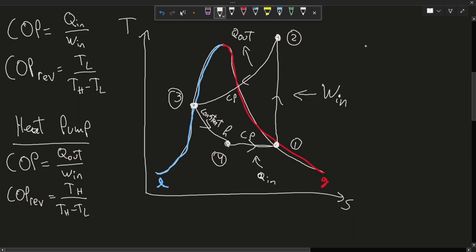One last thing. Unlike the Brayton cycle, we're not going to measure the work done or the Q with Cp delta T. Here, you're supposed to have the tables for your refrigeration. For my final exam, my professor just gave us the values for the H's, but you have to check with the pressure and temperature, and sometimes also the entropy, to find the enthalpies.